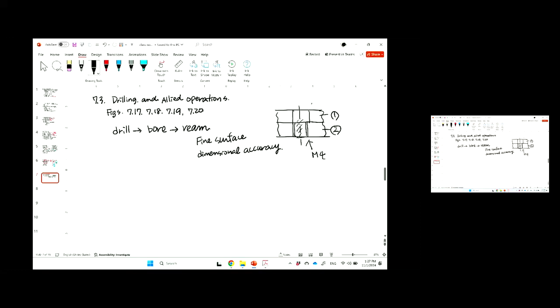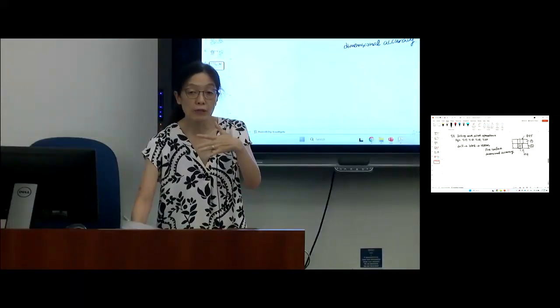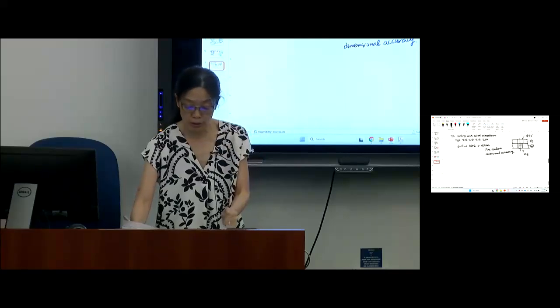But then you will have this hole. This is millimeter, metric, okay? M4 is what we're using. So then maybe you will have 4.5 or something a little bit bigger, right? But you don't need to worry about the surface roughness or something, right? Then it's okay, because you don't need it. But if it's a bearing seat, that's a different story, right?